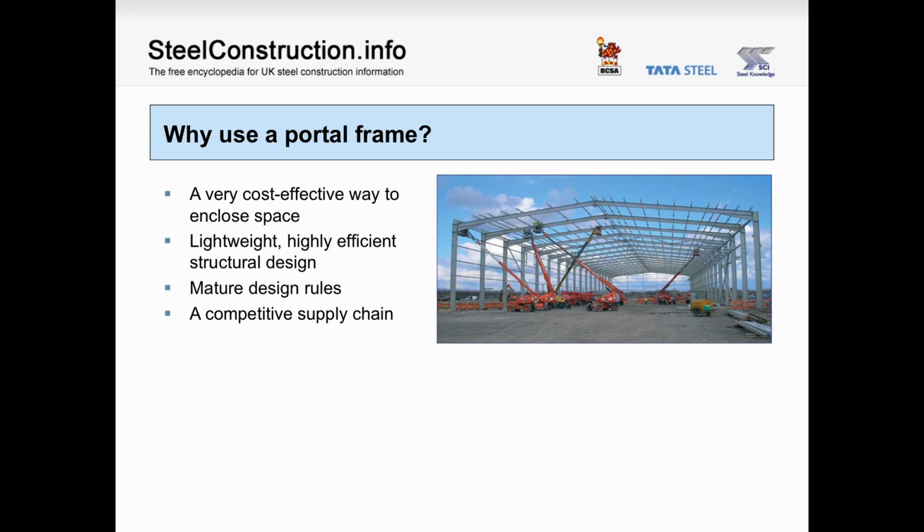Portal frames are very common. They're very cost effective, they're very structurally efficient, they are lightweight, and that lightweight is both the superstructure and the foundations. There are mature design rules, especially in BS 5950, which has sections specifically devoted to portal frame construction.